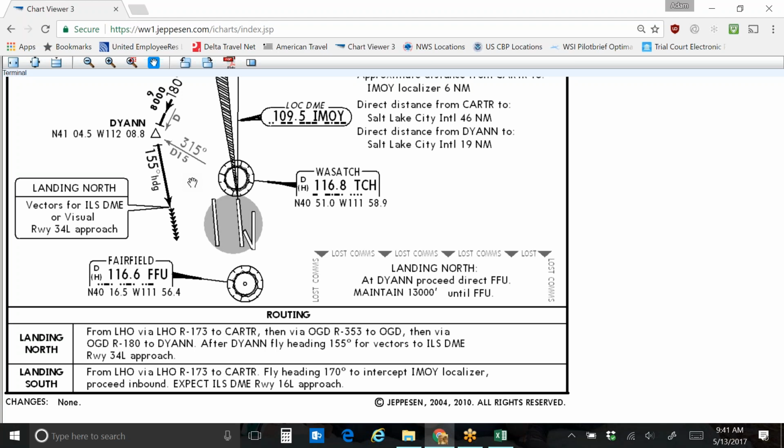So even in a commercial aircraft like ours for SkyWest, as we fly into St. George, even the commercial airplane has to get onto the CTAF frequency, and they have to talk to everybody, because if the SkyWest flight doesn't get on there and start talking to everybody, then these little guys aren't going to know that they've got a big jet coming in. So the SkyWest flights typically at about Cedar City will tune into the CTAF frequency, and they'll start announcing their position.